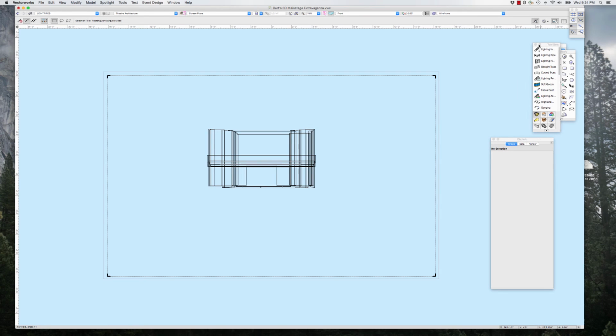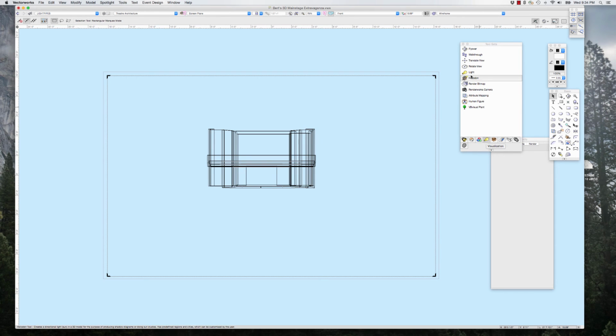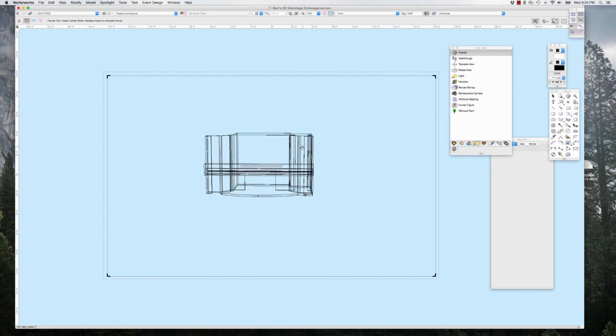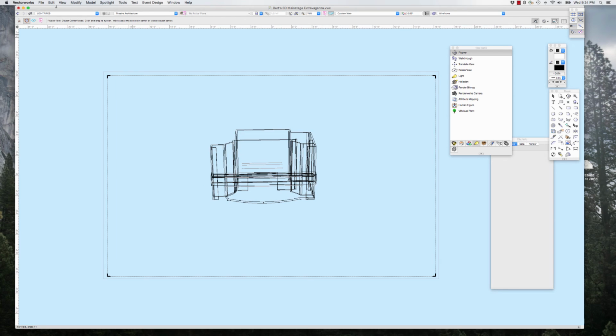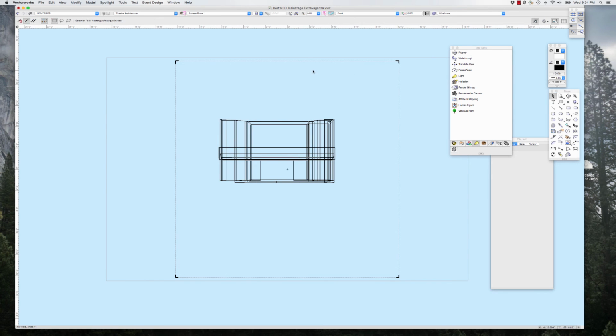So what I'm going to do is go to the tool set here, that's not right, the tool set with the light, which is sort of the viewing tool set. And I have some options here. I have flyover, which is the same thing that we always use. If I use flyover, I've got our normal flyover. I'm going to undo that. When I fly over, it does change the viewing that I set up in Set 3D View, where I set myself out in the house. As soon as I fly over, it changes that.